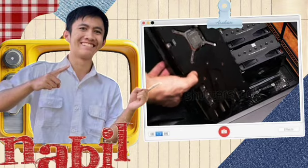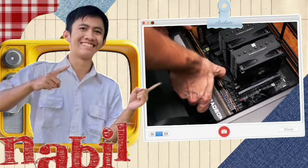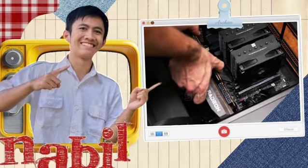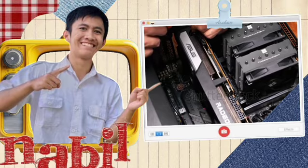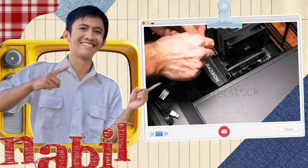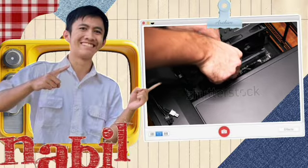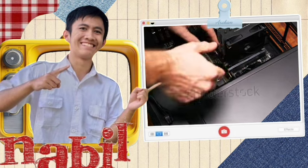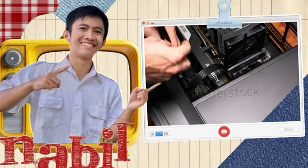Step 9. Installing the graphics card. Locate the top PCIe x16 slot on your motherboard. Remove the corresponding metal brackets on the back of the case. Then insert your graphics card straight into the slot until it clicks. Secure the GPU with screws, then connect the PCIe power cables from the PSU to the GPU. Make sure your GPU is properly seated. This is a common first-time mistake.